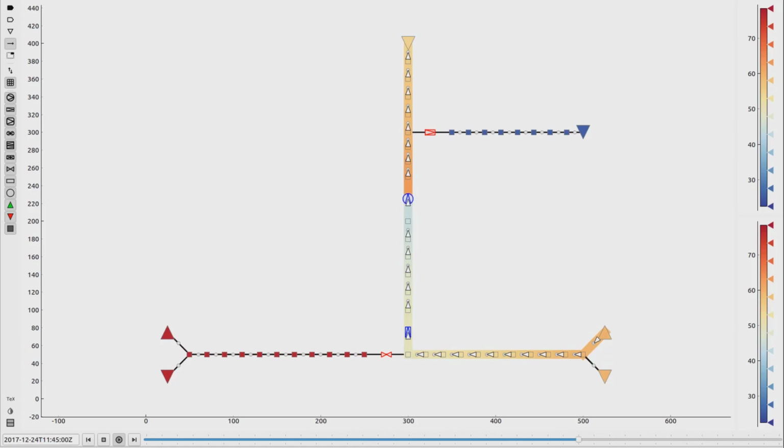At last, we will also turn on the remaining control valve to regulate the gas flow into the low-level pressure area, since the exit in this area will start withdrawing gas now as well. That was our small example on gas network control. If you like, you can skip back in the video and rewatch the animation a few times to really see and understand the interaction between the modes of the active elements and the physical quantities in each of the different areas of the network.